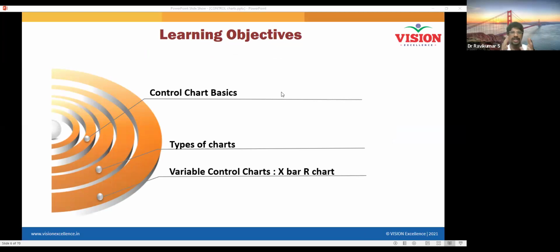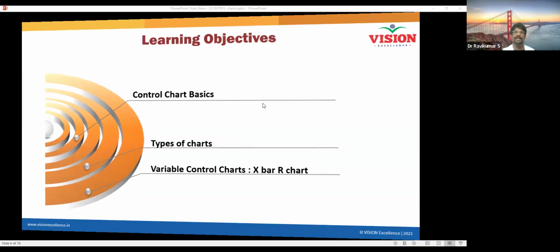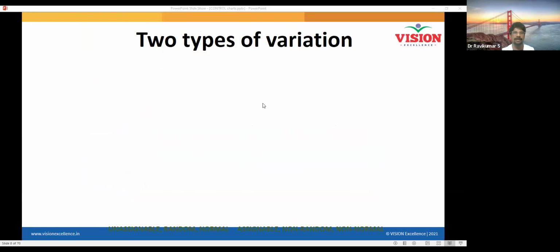Okay, guys, do you get it? Why are we monitoring the process? We want to monitor the process so that the root cause doesn't occur in another way, in another format, in another kind of features. We don't want that to happen. So we want to monitor the process and find out if there is any deviation or fluctuation happening in our process. Deviation means variation beyond the control limits, variation beyond the acceptable limits. That is considered as control deviation. So when that happens, you need to be aware of it. For that, you need to keep on monitoring the process.